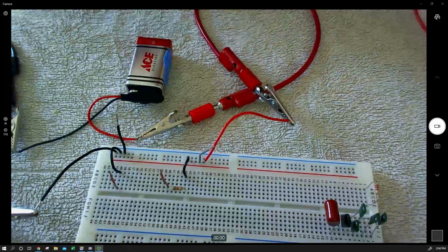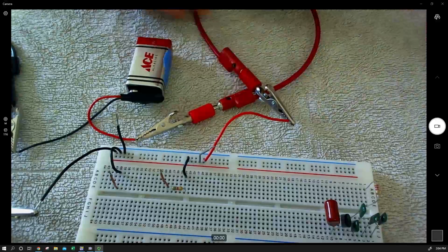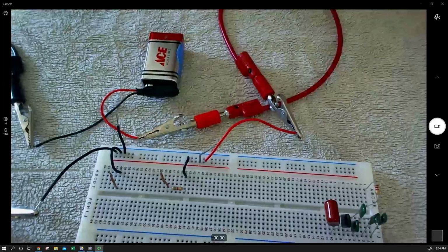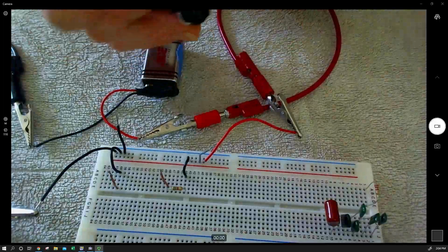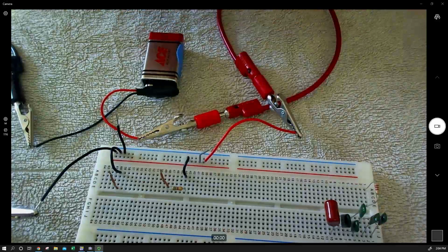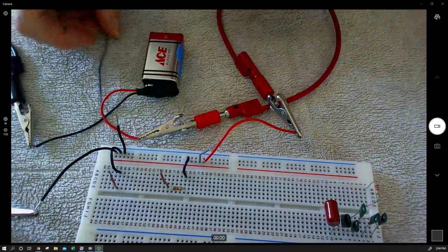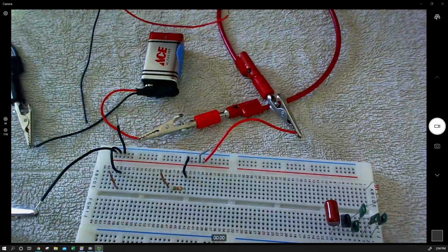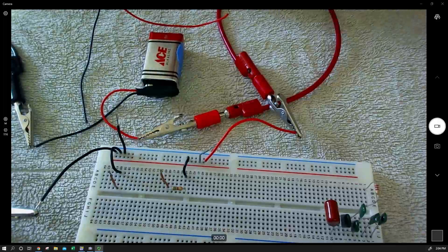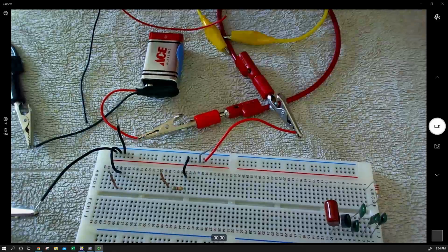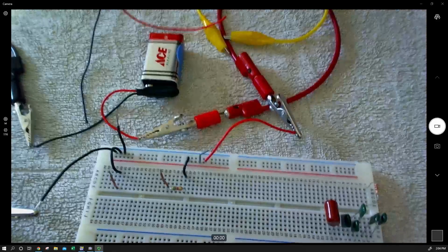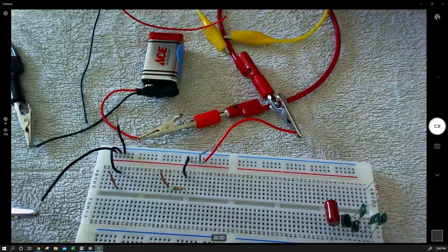So if we were to look at, okay, let's put another battery which has the same nominal open circuit voltage, what would happen if we put that battery in parallel? Are we effectively going to get double the current? Probably not, because we are fairly close to what Ohm's law would limit us to. So in fact, let's do a quick offline calculation. Always good to calculate while you're in the lab.